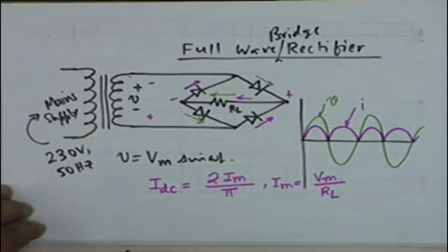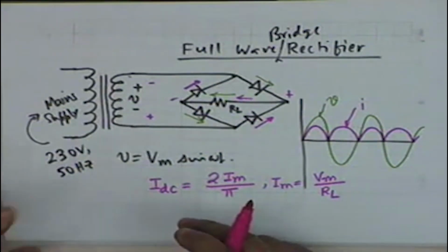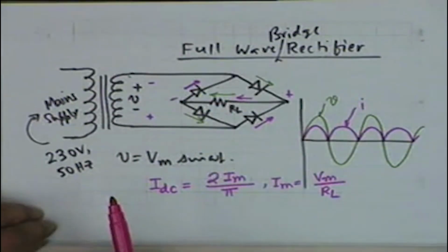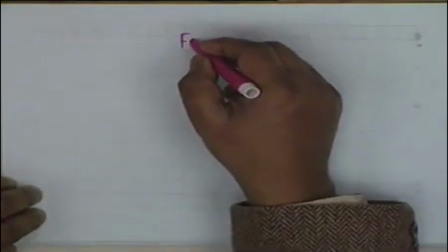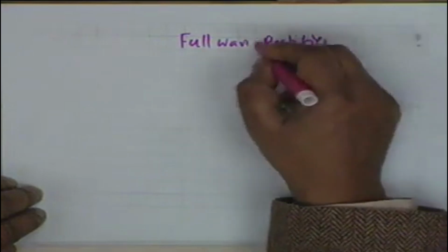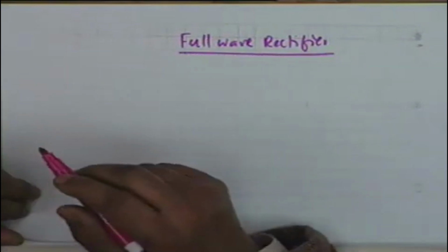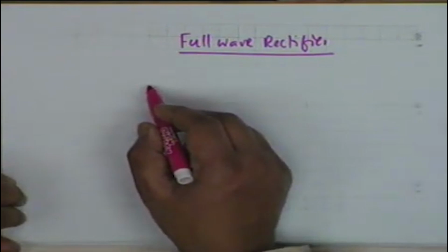and therefore this is a disadvantage. But the advantage of this circuit as compared to the one that we are going to discuss now, using only 2 diodes, is that the transformer becomes inexpensive. Why? Because in the alternative circuit for a full wave rectifier, using only 2 diodes instead of 4 in a bridge requires a transformer which is to be center tapped. That is, I require a transformer like this.